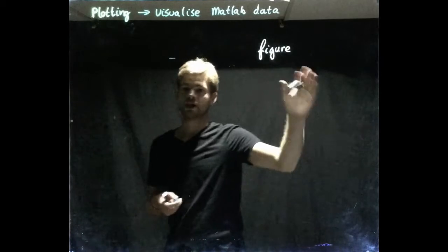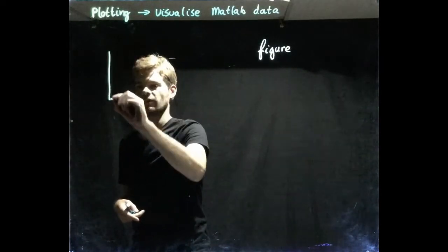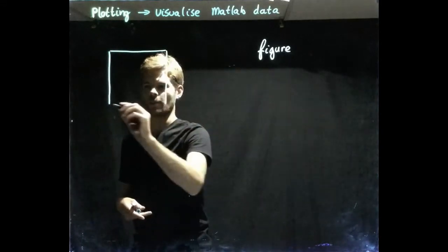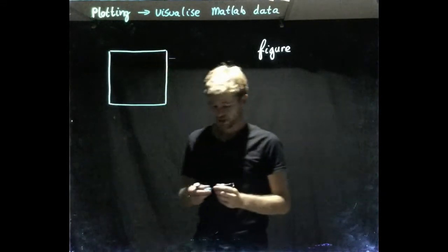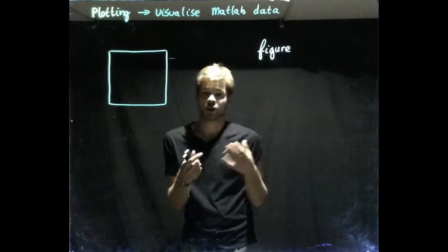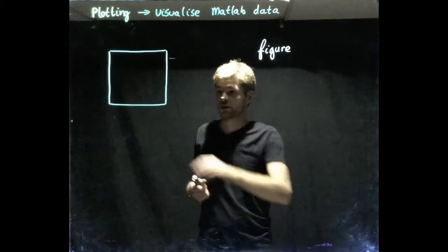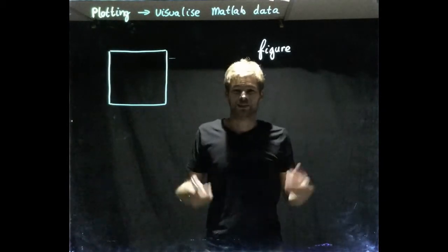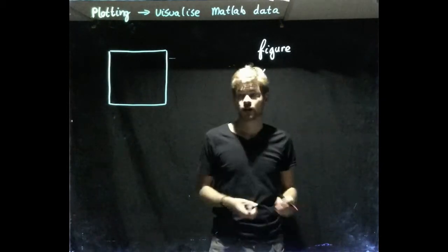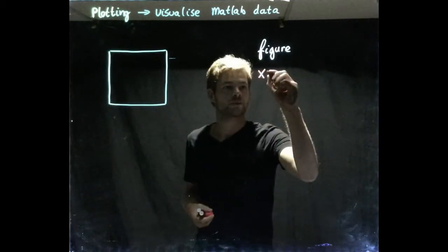That's the command. If you write this in the command window, a screen like this, a box, will pop up. And if you want to make a graph now, your graph, well, you will need some input. You have a plot command, and the plot command that's going to create your graph needs input. So I'm going to define the input first. Actually what I want to do now is to plot a sine wave and a cosine wave as well. So I'm going to write this down.